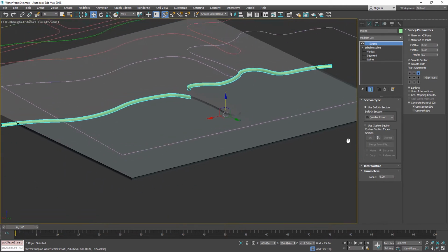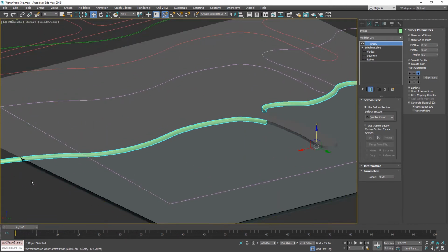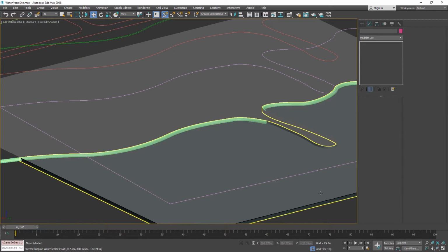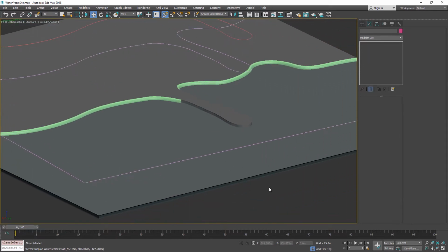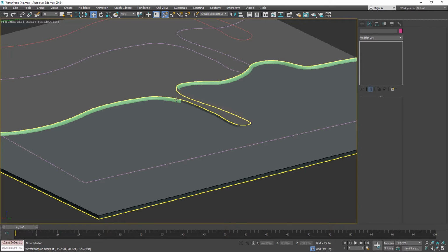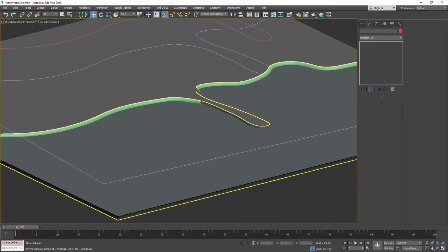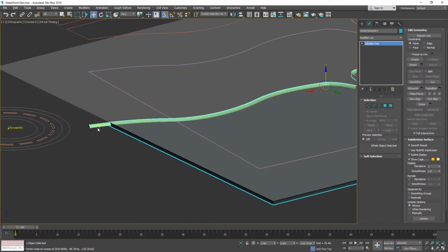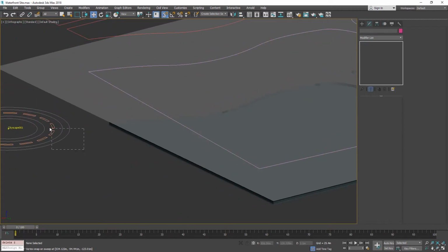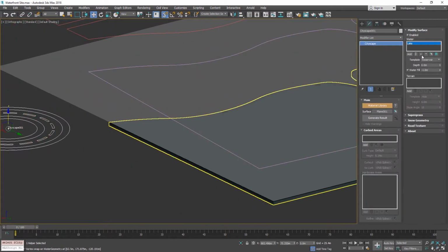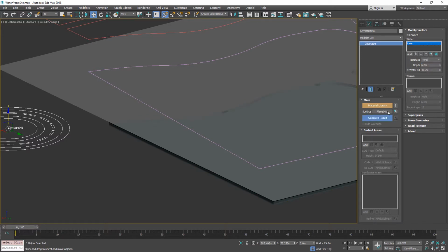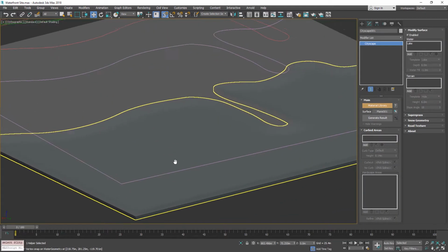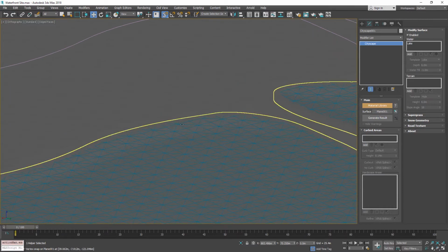If you have a complex waterfront site, it's probably better to start with a reservoir template and then just create the custom beach models manually. Otherwise, if you have an even surface everywhere, even slope everywhere, you can just go ahead and use either reservoir or pond template, and it just gives you the same gradual slope everywhere.